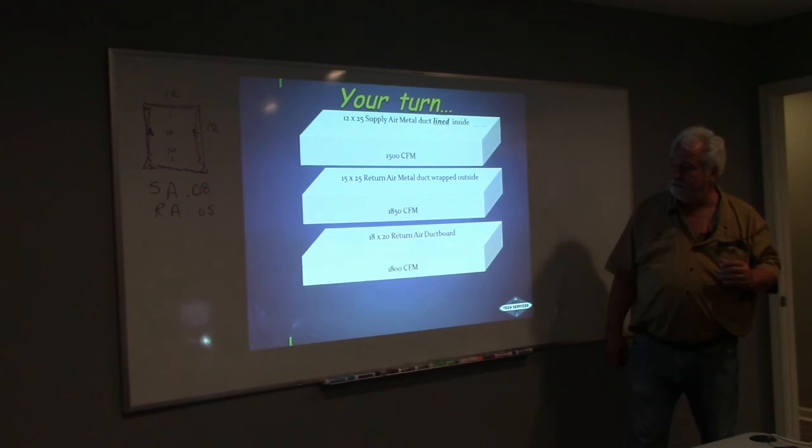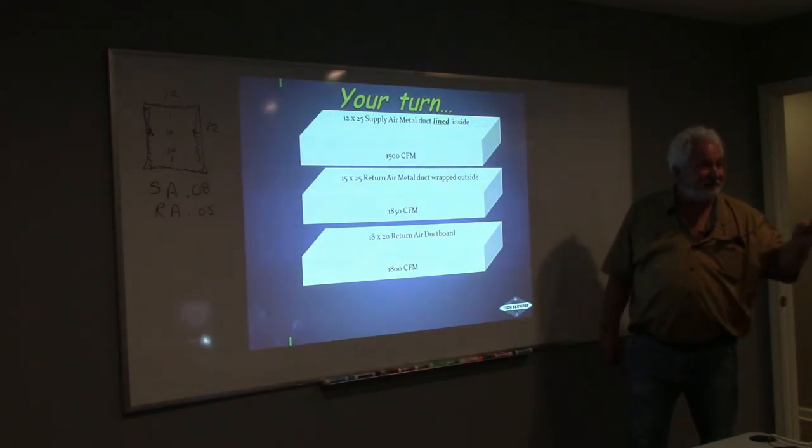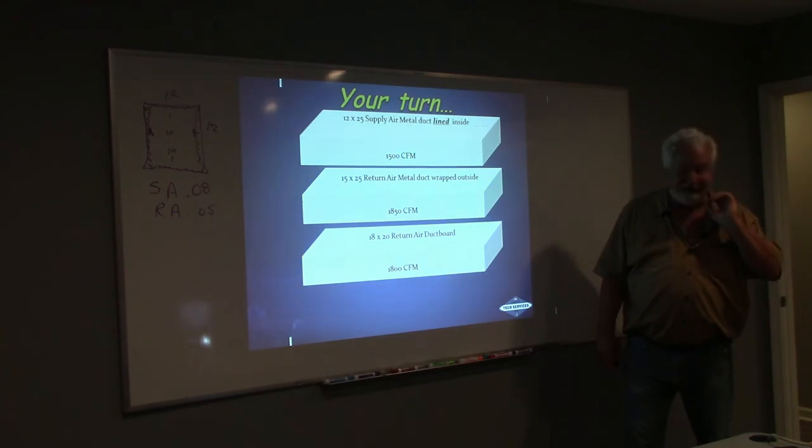Duct board. Where's duct board? Bottom right. Good. Okay, so it's a return, so it's 0.05 right there. Duct board doesn't give you 0.05, you have to look between the two numbers, the lines in between. Yeah, I got you.